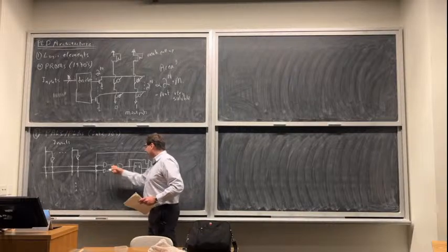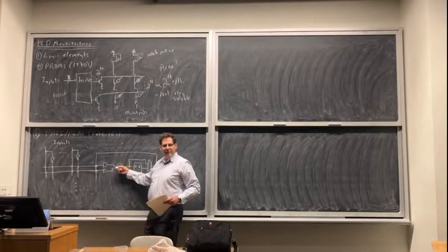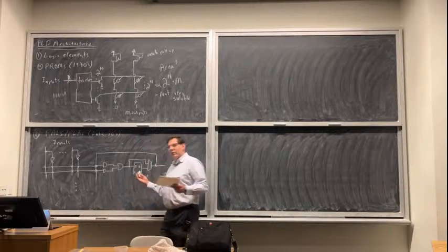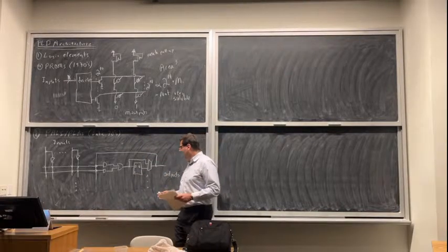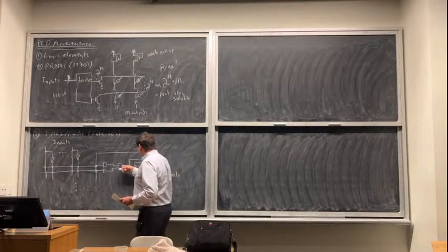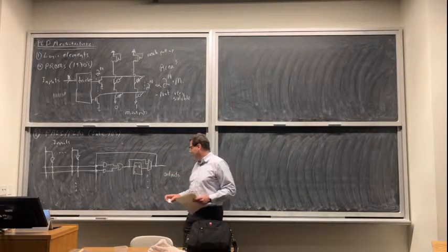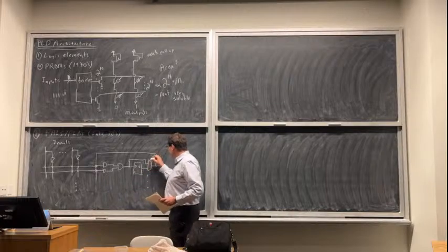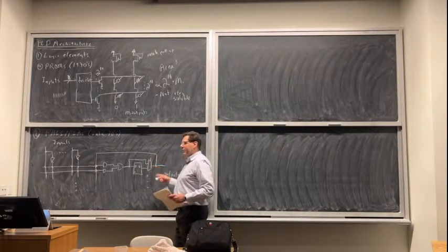I have some number of these AND gates. Here I've taken 2, and they go into an OR gate. And that's two-level logic, right? So you can do anything with a combination of AND and OR. That wouldn't be enough to do sequential logic, and by this point, people want to do sequential logic too. So you put a flip-flop in, and a multiplexer that you can also program to allow you to do that.